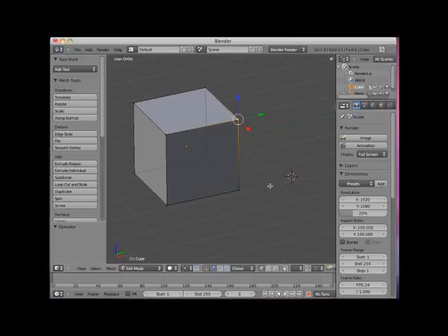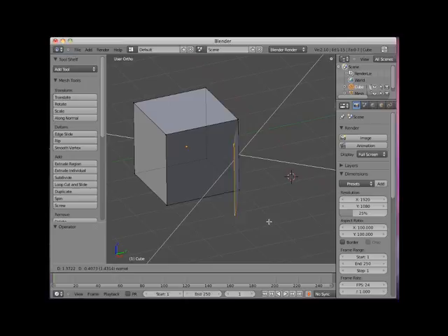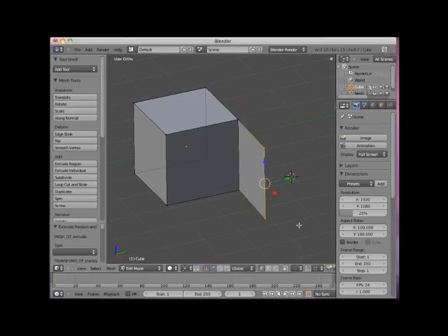I will select the two right vertices of the cube, thereby implicitly selecting the right edge, and then I'll press the E key to extrude. Note that there are two possible normal axis lines, and Blender does not constrain the extrusion to either. I can move the extrusion anywhere in grab mode and left-click to place it. Notice that the extrusion now includes the edge subcomponent, and thus the extraction creates a new face formed by the four edges. In Blender, this is referred to as a region extrusion. That is, the associated edge, or edges or face as the case may be, are extruded along with the vertices.